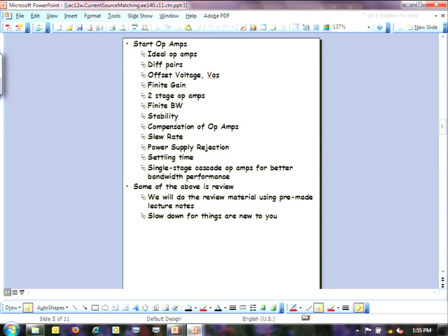Okay? And so naturally, if that's an ideal voltage amplifier, then this leads to our concept of our ideal operational amplifier, where the operational amplifier just differs from the voltage amplifier in that it has a differential input. Okay, so there's a question, why do we want that differential input? We'll talk about that in a second. That has to do with noise. Okay, the differential input actually knocks out a lot of circuit noise